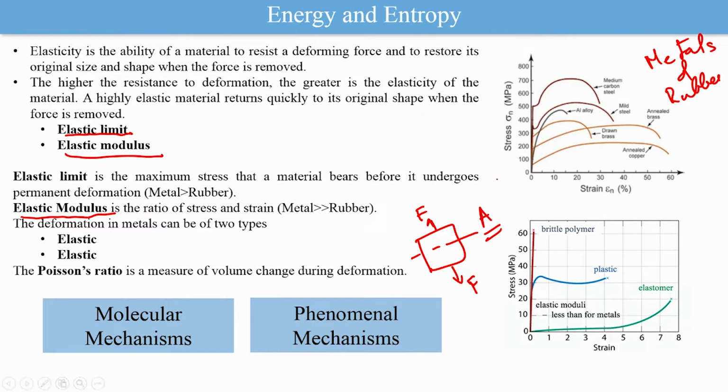This we might have studied in school itself. So, this stress sigma is equal to F by A. Okay. Now, what is strain? This basically when we apply this force, an elongation happens by say amount delta L. Okay, this is total displacement on both sides, okay, together. If it is delta L and the original length was L, okay, then the strain epsilon can be expressed as delta L by L. So, this is the strain basically.